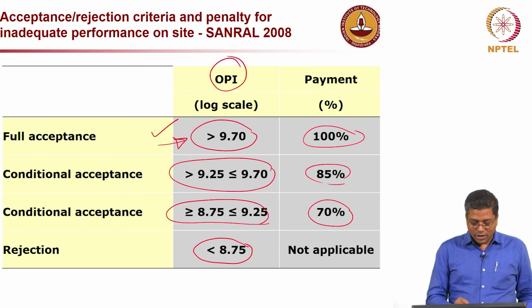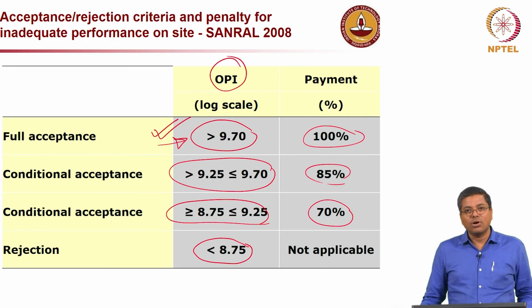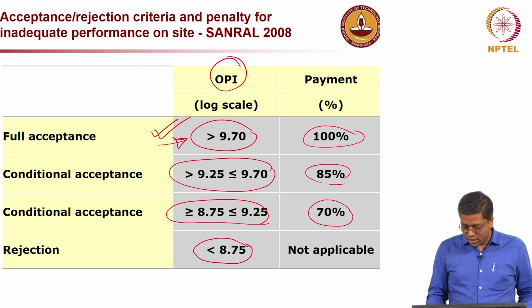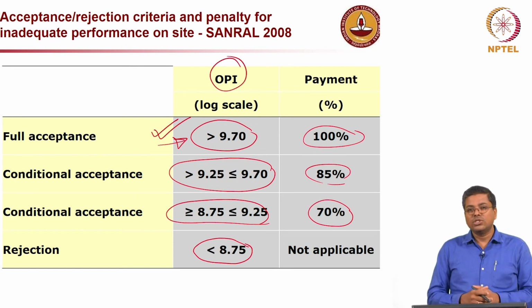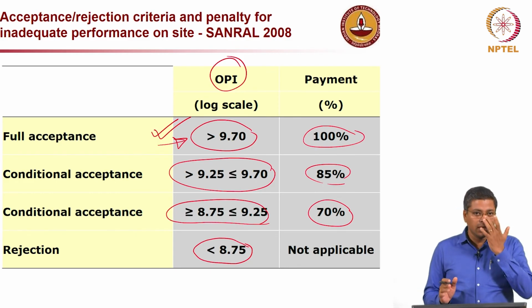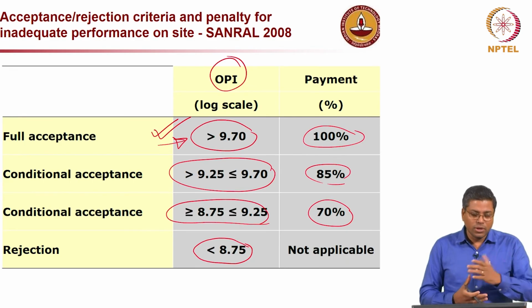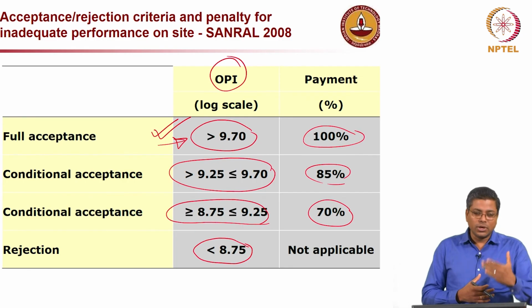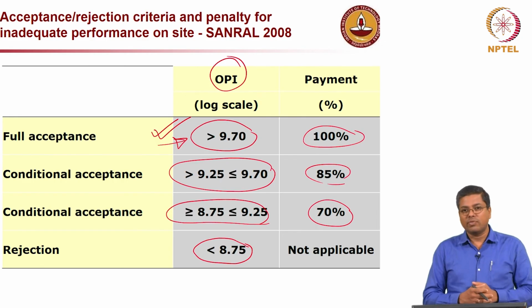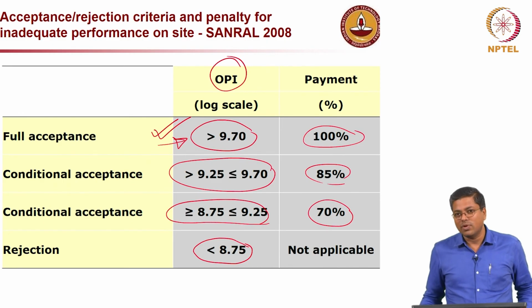That means no issue, and at the same time the concrete structure was also found to be highly durable in nature. So, this is one way of ensuring durability, either for new construction or for repair. All you have to do is define a particular performance indicator and/or a performance test, and then put it in the contract that post construction or post repair this particular type of test will be conducted at random locations, and based on that only payment will be released.